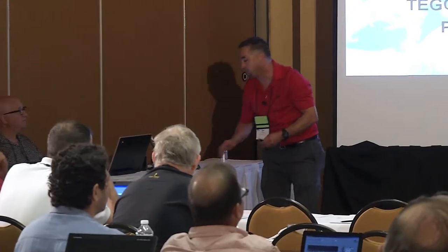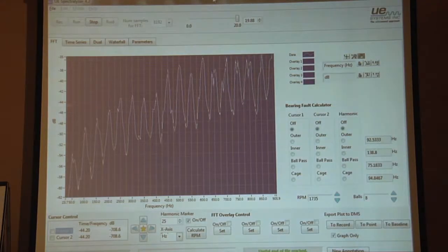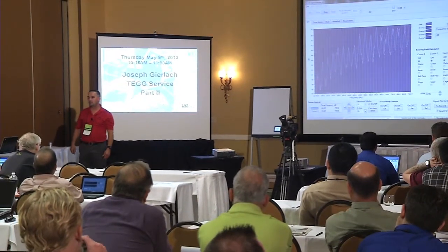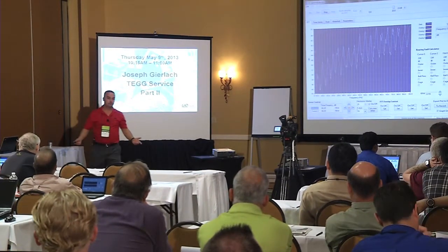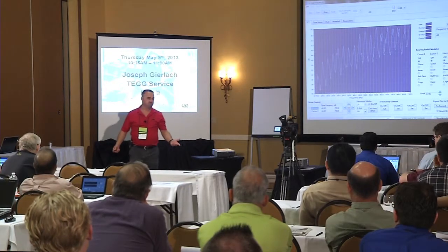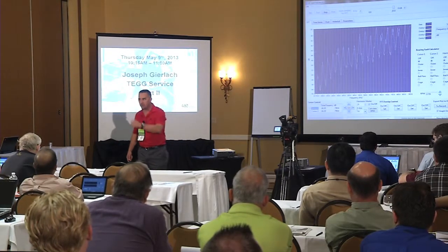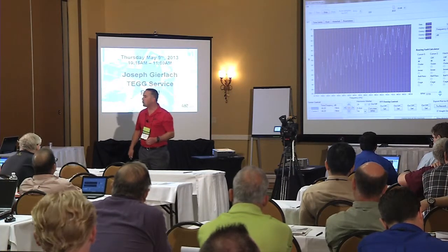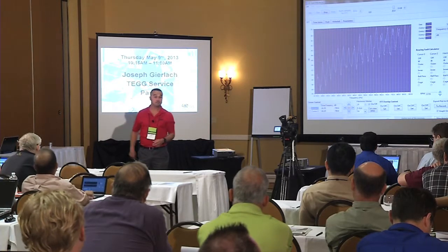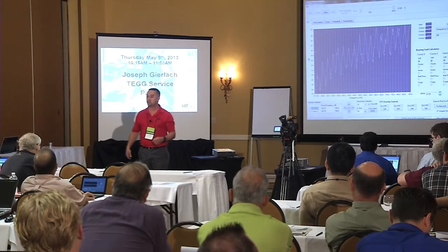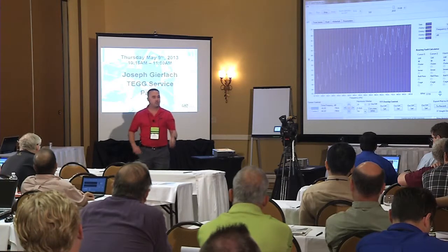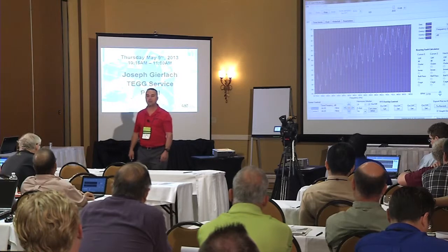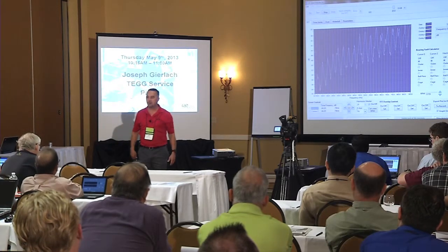And Peter just asked the question about what the heck this could be. But as Mark pointed out, what do you not see in between all the harmonic markers, ladies and gentlemen? No noise at all. Is that a problem? No. The 25 hertz we need to find out what that is, but let's say that isn't there and I see this spectrum. Is that normal for a transformer operating under load conditions? Every time. The 50 or 60 cycle hum is going to produce that type of spectrum that lacks the frequency noise. There's nothing wrong with that.